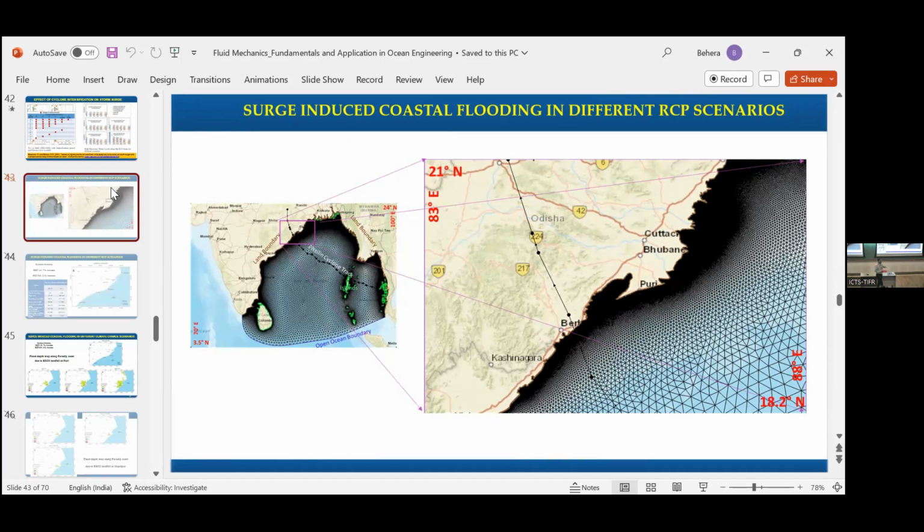So flood depths, we separate in every 1.5 meter approximately. The reason is we consider our standard normal height, which approximately you can see up to this, so one person can survive. So we do a classification like that, and then based on that we do a zonation.